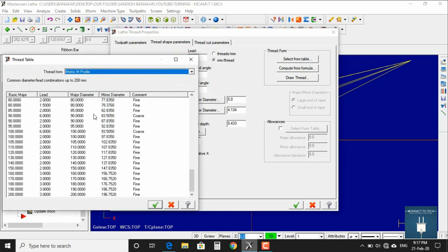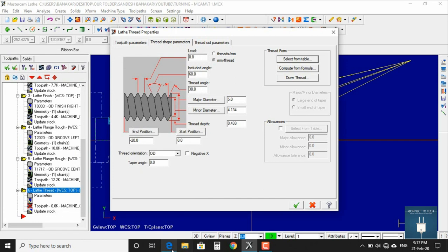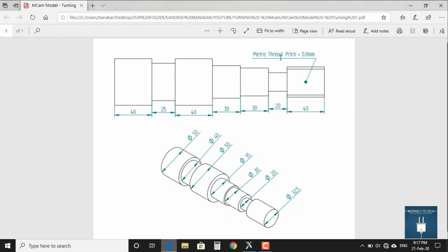This is by the design calculations, the basic designs, how you calculate the thread dimensions by the design formulas you have. So this decides based on the design formulas. So we don't have the formula here, we just have the ready-made pitch 0.8 mm for the 32.5 diameter. Remember, 0.8 mm pitch for the 32.5 diameter part.